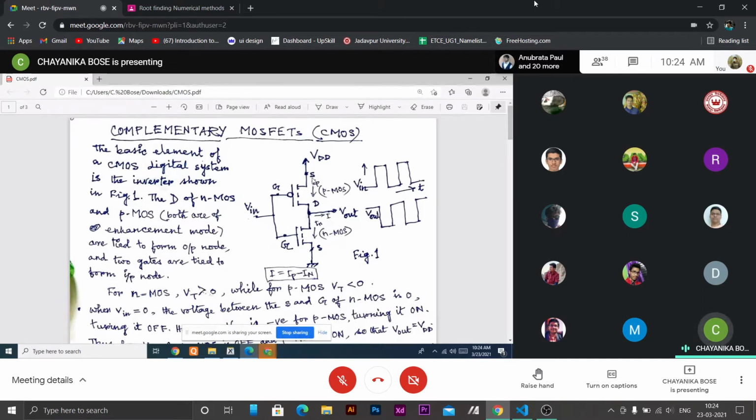So for PMOS, the channel holds positive charge, so drain must be at lower potential than source. Source is 0, drain must be negative or low because its purpose is to collect the holes supplied from the source.